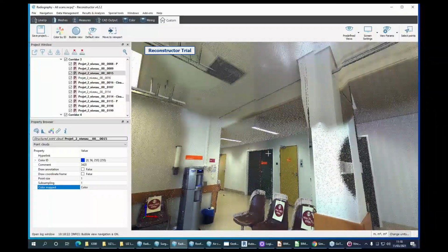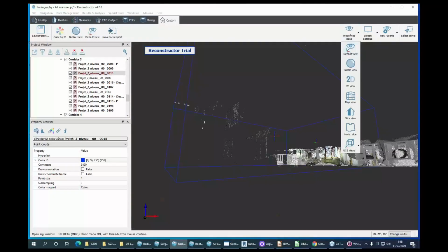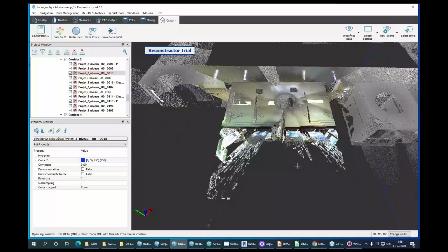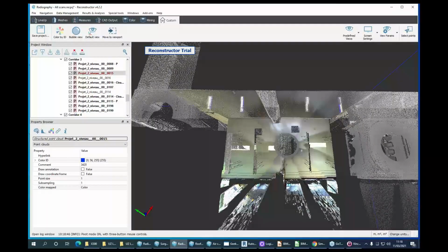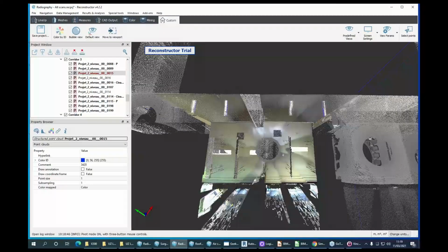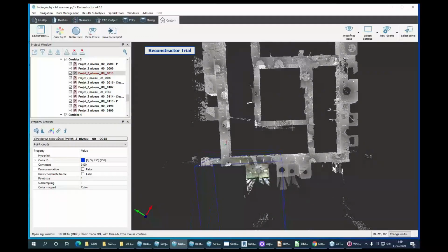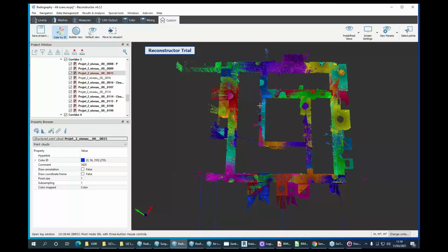On this one, as an example, we would typically do 2 scans, one on each side of this little pocket. I don't know the correct term for that. It was a waiting room actually. So we did probably 2 scans, or actually only one, in this little pocket, and then we had scans in the corridor so that we could see both of these waiting rooms and the corridor. We spaced them according to the number of waiting rooms and nooks and crannies we had. So it's not a fixed regular interval. It depended on the specifics of the place.